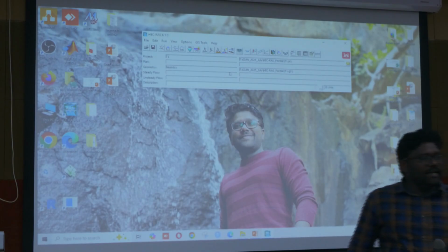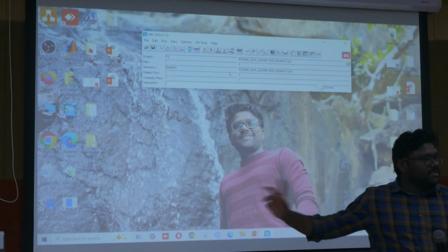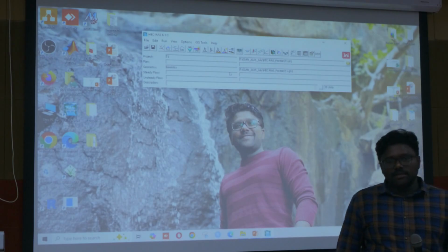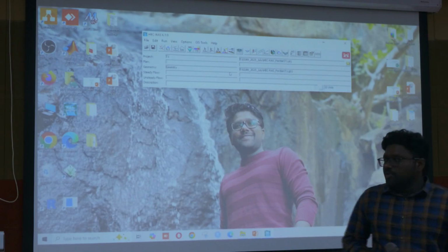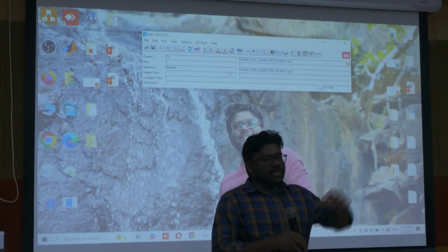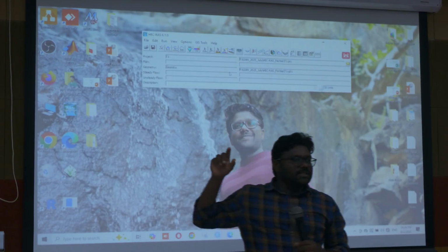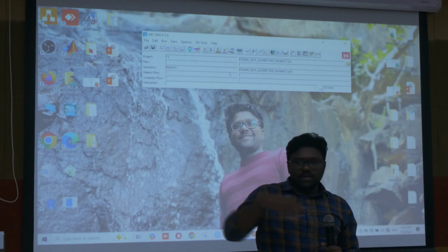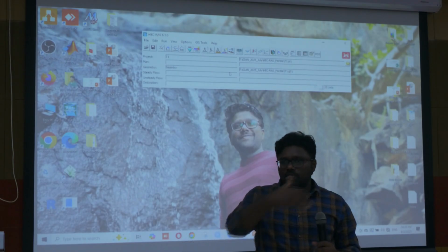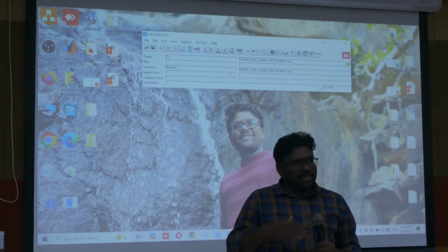So, till now, what we did, we created the geometry and we have assigned the roughness in the main channel, the right bank and left bank, right? Now we need to flow the water from upstream to downstream, right? So our flow was unsteady, right? So we have simulated for the event, so it is changing with respect to time. So our flow was unsteady. Let's see both steady and unsteady. First we will try unsteady.